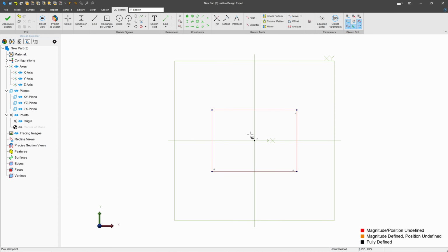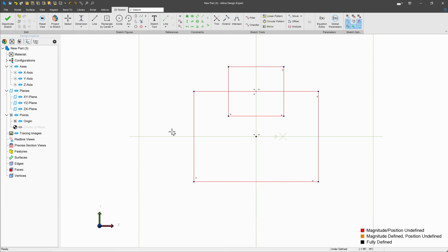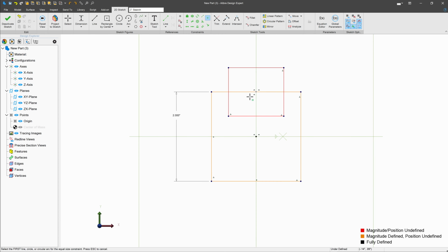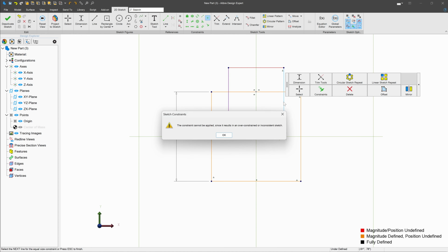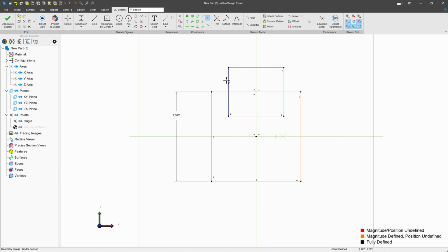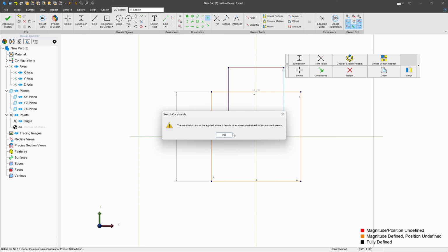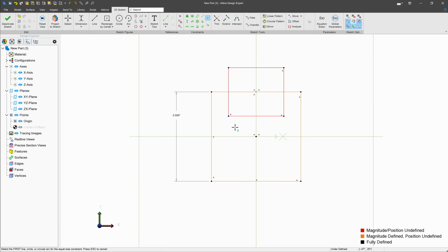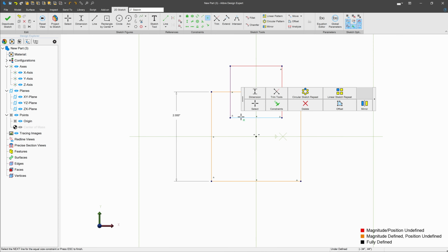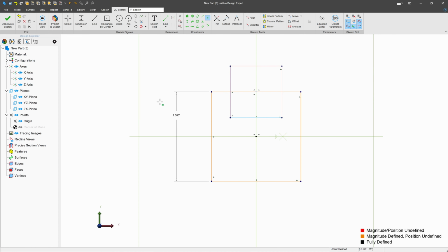just like that. And then maybe I'll select the midpoint of my line and make another rectangle by center. And then I'll give these dimensions. We're going to say 2 here. I'll grab an equals from here to here, just like that. And then I'll make sure that this is equal so that we're dealing with some squares. And oh, you'll notice I chose these 2 vertical lines, and that does indeed produce an over-constrained sketch. So it's pretty handy to have those warnings on. We'll say equal there, and that's what I meant.